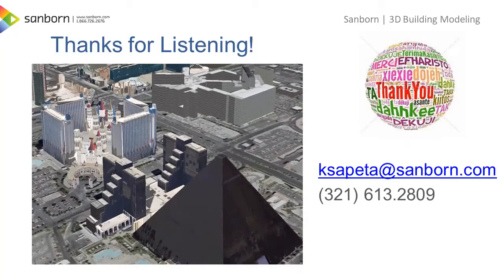We then incorporate that into the LiDAR model, and we flatten and enhance that LiDAR model with the water, and then from there you can go on to doing different types of hydrologic modeling. When we're building this water model, we make sure it has monotonicity, which means that everything flows downhill in the way it should.